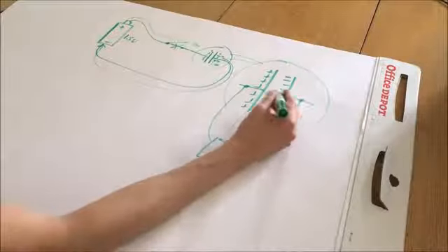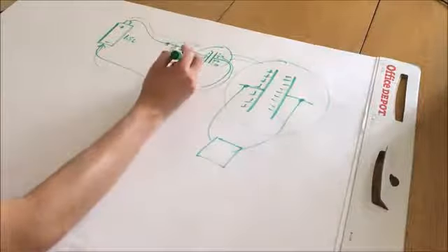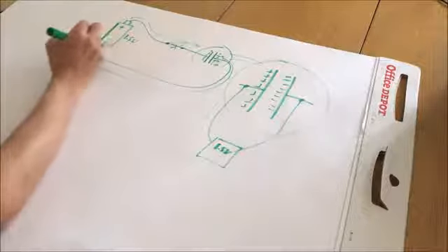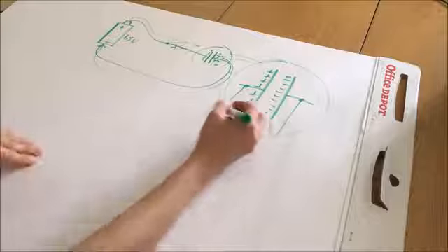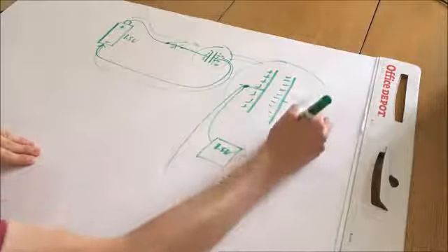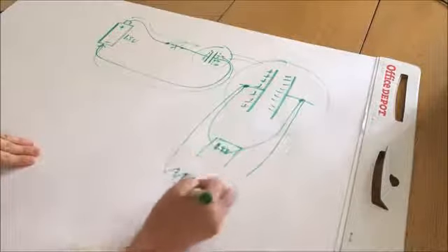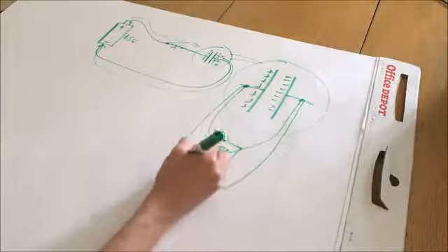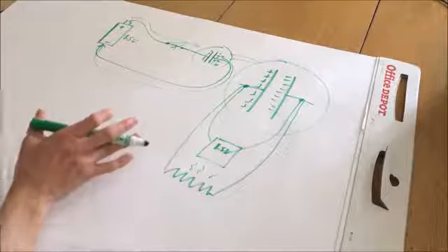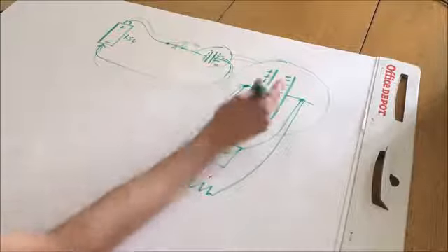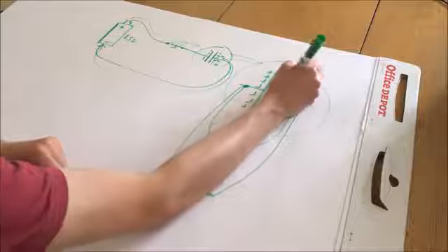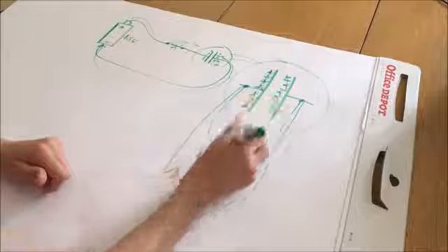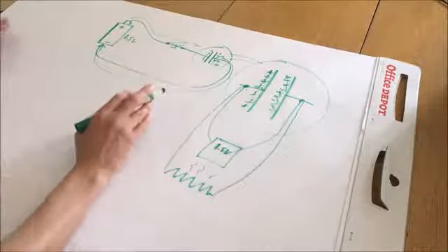Well, this capacitor, assuming there's no leakage current through it, is going to stay at 1.5 volts, even after the battery's been disconnected. And if you were to then connect a resistor of some value across it, this would gradually discharge the capacitor, and in exchange, it would produce heat and do work, as we saw, until the capacitor finally discharges so much that it no longer has any significant polarity of voltage. It's back to its original state.